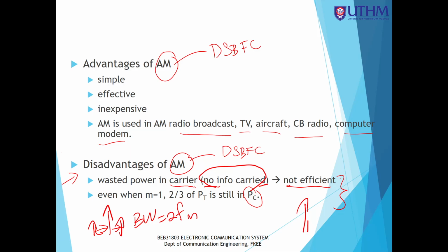The station broadcast frequency is 810 kilohertz. So this is using the AM band. So what is this actually? The broadcast frequency is referring to the carrier frequency. So compute the following. Calculate the lower and upper sideband frequencies. Now you have FM, you have FC. So the FLSB is FC minus FM. FUSB is FC plus FM.